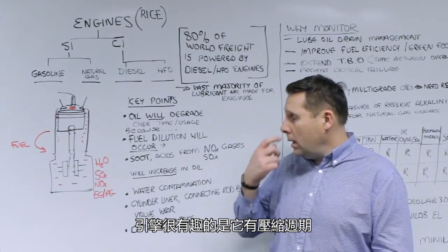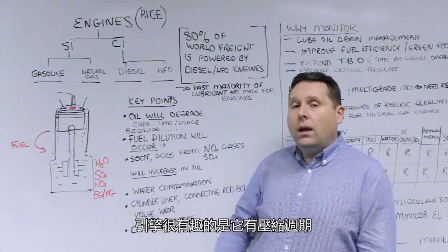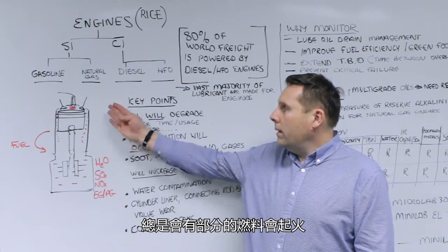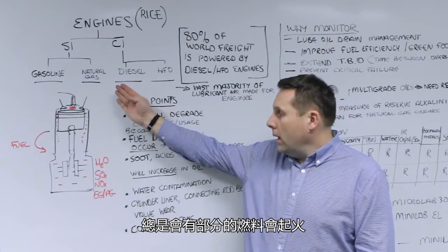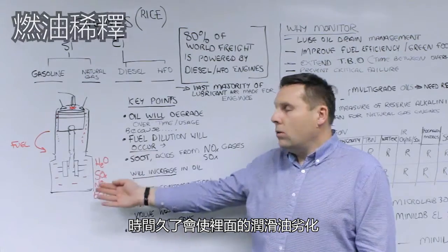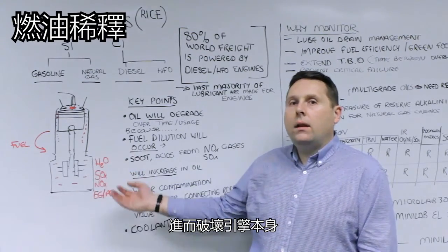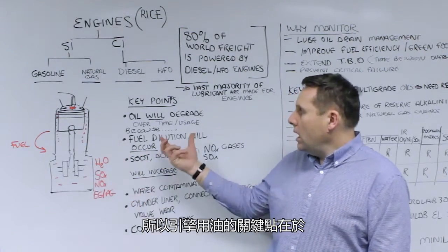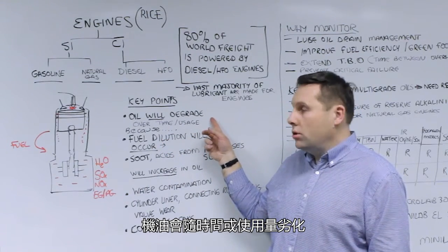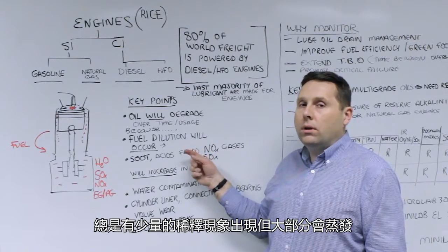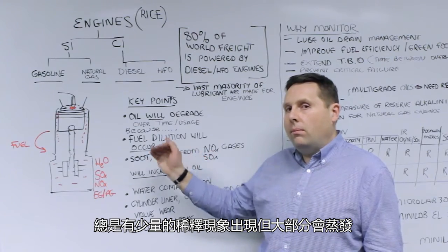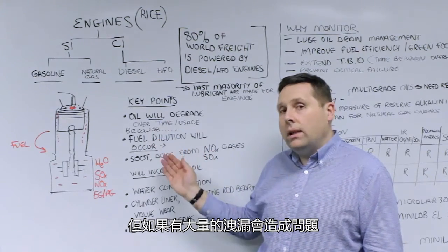Well, what's interesting about an engine is because of its compression cycle, you're always going to get some of the fuel that you are burning somehow getting into that crankcase, and so over time that's going to actually degrade the oil and then potentially damage the engine. So key points for engine oils is the oil will degrade over time and usage. Fuel dilution will occur. There's always fuel dilution getting in. A small amount, most of it gets boiled off, but if you get an excessive leak, you're going to have problems.